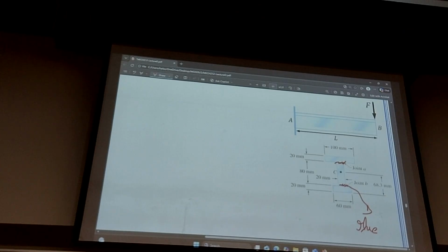Because it's not symmetric, look at the upper piece and the bottom piece. Because they're not symmetric, the centroid is not exactly midway of the total height. And we calculated centroids in statics, and also we reviewed in this course when we looked at the T-shaped cross-sectional geometry. And we did about 10 calculations for I.